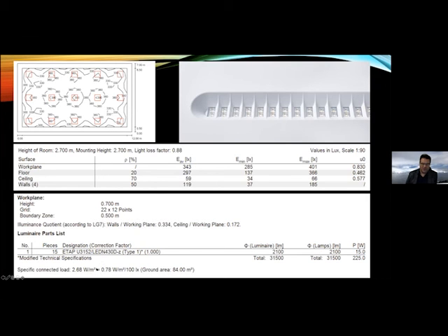Okay, some people are looking into this 0.78 watts per meter squared per 100 lux. I generally do not look into it. I know where this is all coming from, and I know this figure could be reduced if you install luminaires which are not really illuminating walls. To me, this is the key point. How many watts per meter square we're really consuming, because that figure corresponds to the CO2 emission.